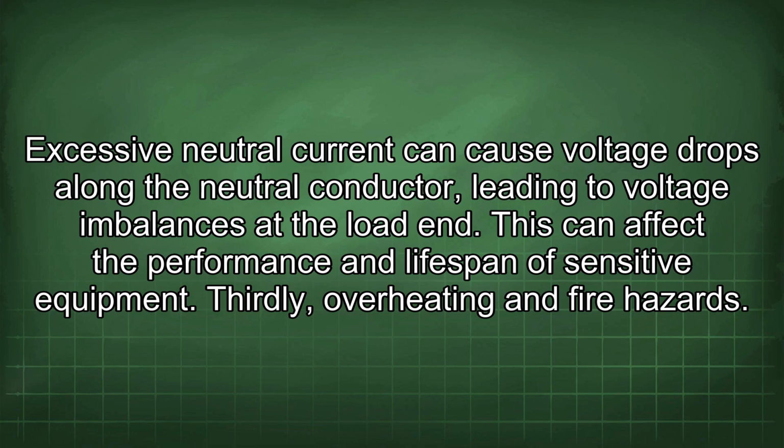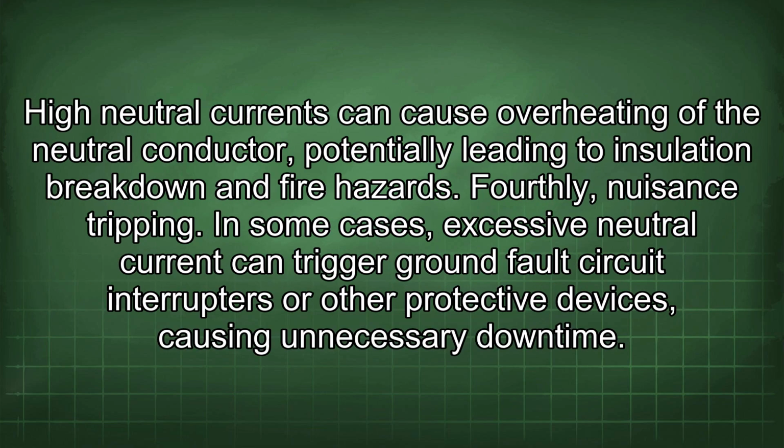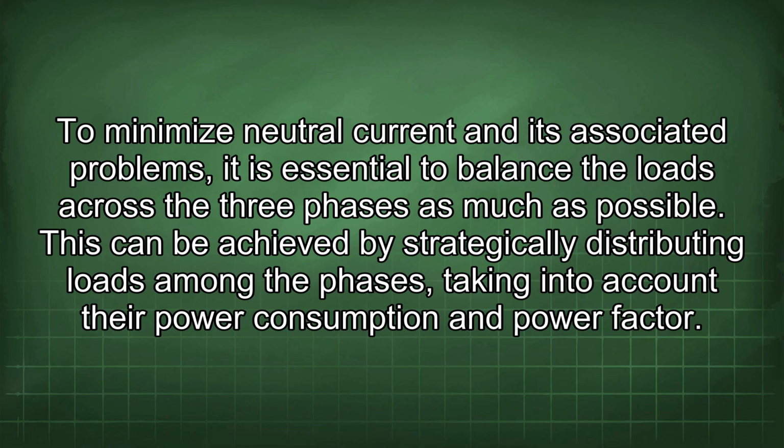Thirdly, overheating and fire hazards. High neutral currents can cause overheating of the neutral conductor, potentially leading to insulation breakdown and fire hazards. Fourthly, nuisance tripping. In some cases, excessive neutral current can trigger ground fault circuit interrupters or other protective devices, causing unnecessary downtime.